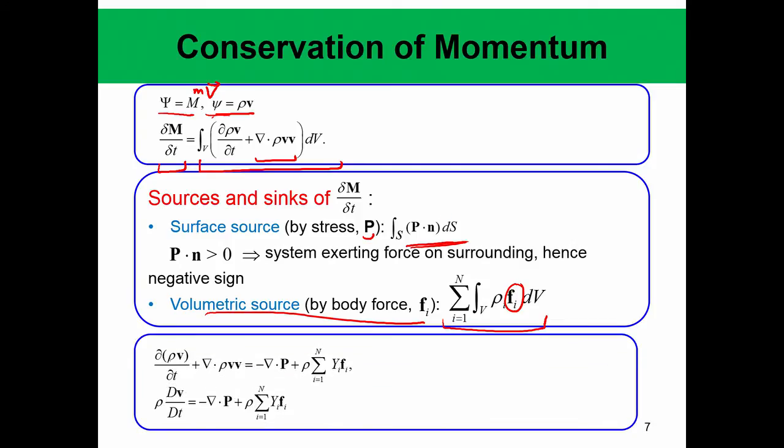So once we convert this integral form to a partial differential equation form, what we get is partial d rho dt, which is the transient term. Then we get this advective term. Both are nothing but the acceleration of the fluid, and this acceleration is caused by the gradient of this pressure tensor, which is nothing but the force.